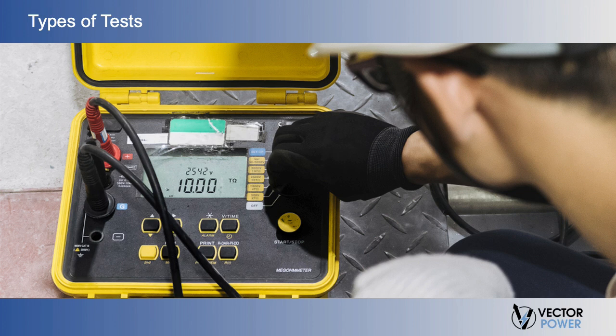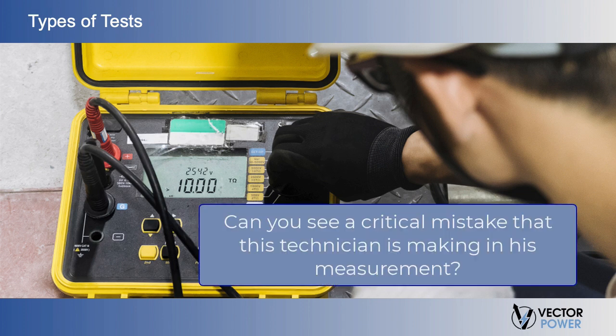Now let's talk a little bit about the types of tests that we can perform. Let's start with the spot reading. The spot reading test is the simplest of all insulation tests. The test voltage is applied for a short, specific period, typically 60 seconds, as usually any capacitive charging current will have decayed by this time, and a reading is then taken.